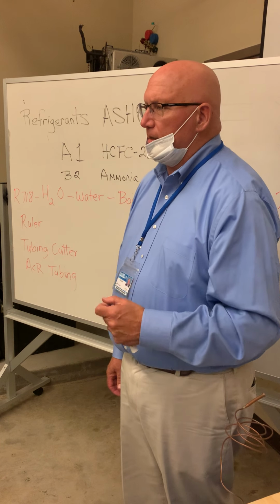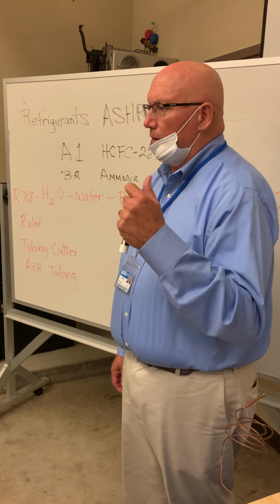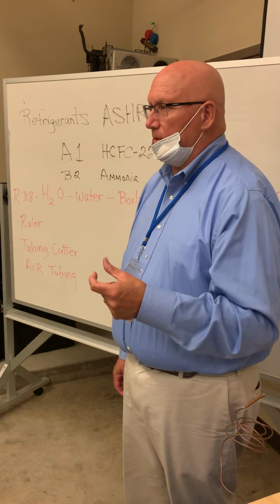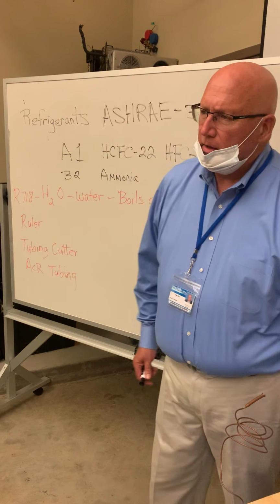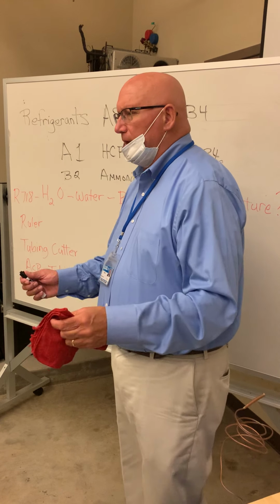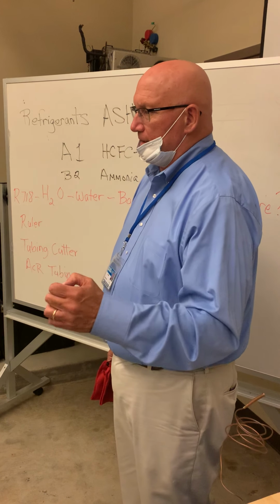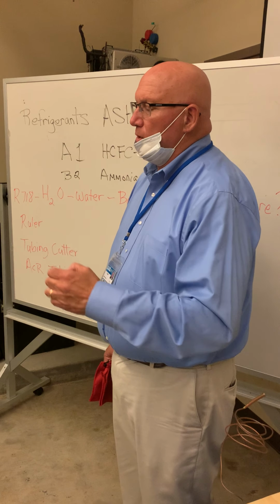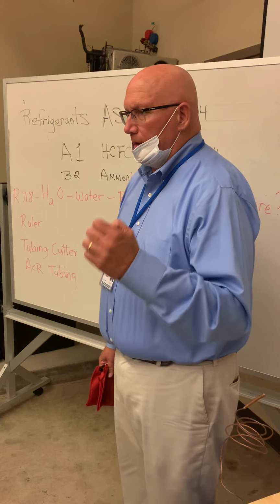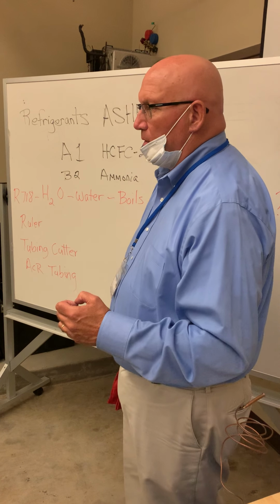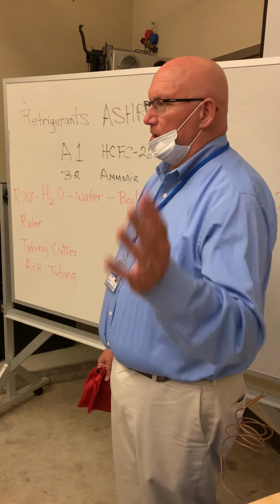So ASHRAE Standard 34 classifies a refrigerant as to its toxicity and flammability. Flammability does not mean that... what it means is, can it burn? Yes. But if you remove the flame from it, it stops burning. One that's highly flammable, you touch it with fire and it just keeps on burning.